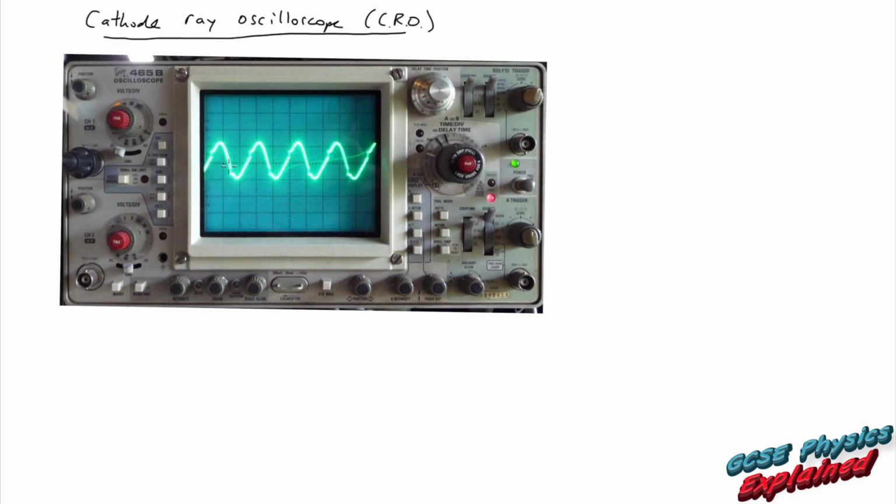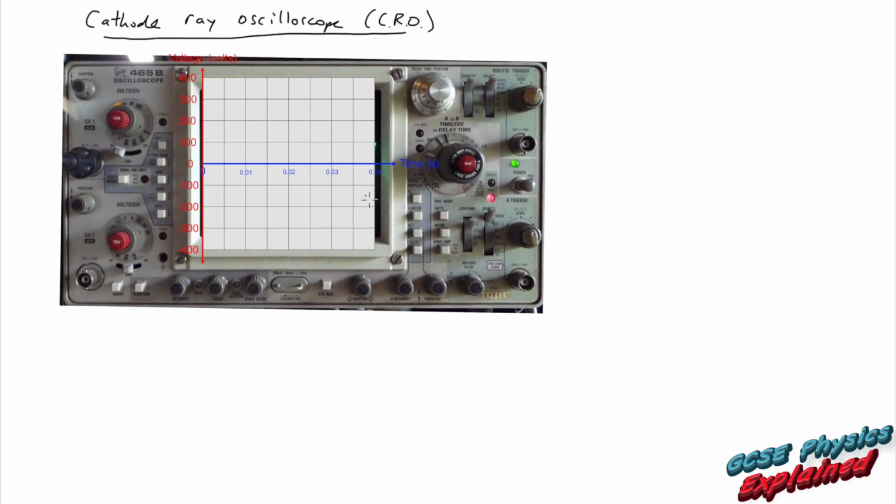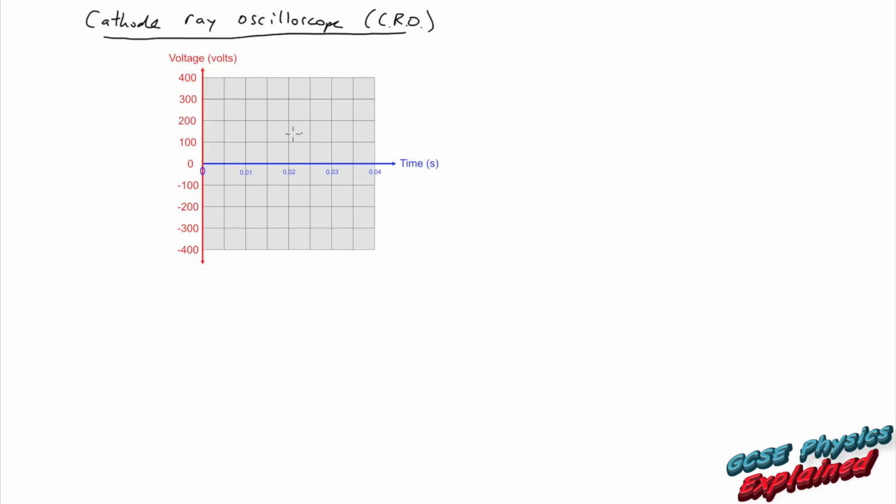And also, going across on the x-axis, we usually have the time, and again you can set it so 1 square across might mean 1 second, or it might mean 10 seconds, or it might be 1/10 of a second, or even 100th of a second. You just turn the knobs and set it so that your picture looks canny. Now what I'll do is put some graph paper over the top of it, just like that, and I'll get rid of the oscilloscope now. It's served its purpose. Right, that's better.